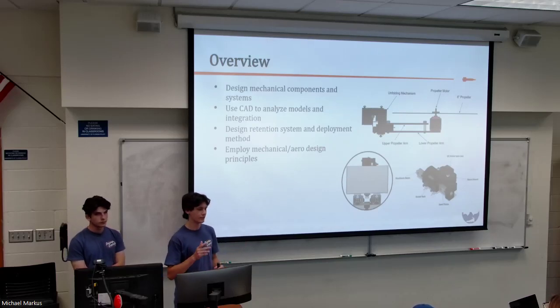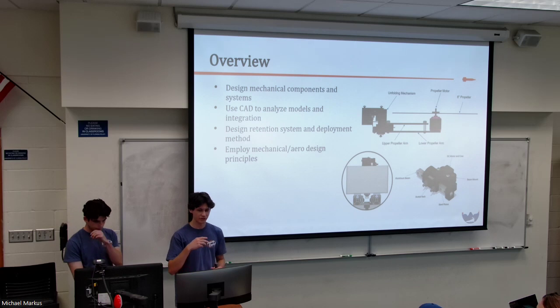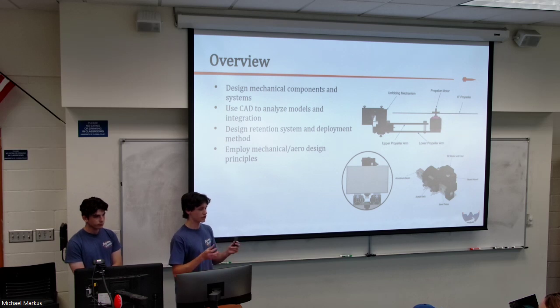And then a pinion is an actual gear that drives the whole thing. So as the rack got moved, it would lock the door in place and stop it from opening. And then when we were ready for the plane to come out, the pinion would turn and retract the racks, and then the door could open and the plane could come out.